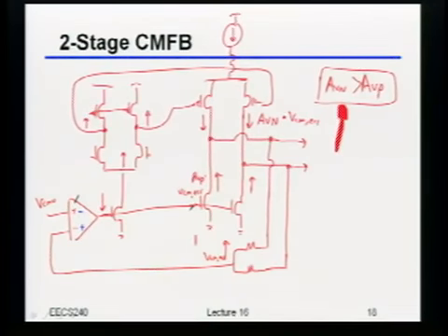Or yeah. Can you just have one feedback loop? I mean, like. Say that again? Can you just have one common mode feedback loop, as we've drawn it here? I mean, like, have the second stage current sources be separate. Yeah, no, I think that's what we sort of had drawn in black before, of basically separating the two loops. So you have one common mode feedback loop for the first stage, and a second common mode feedback loop for the second stage. No, what I'm saying is, like, don't have a common mode feedback for the second stage at all. So how are you going to control the common mode then?